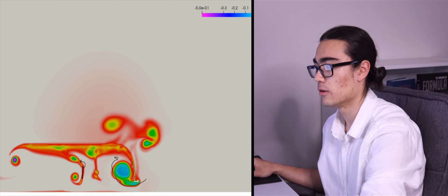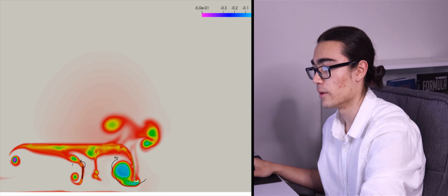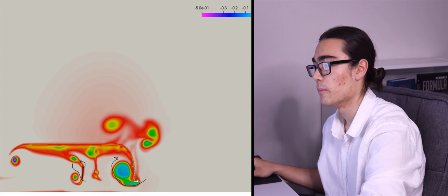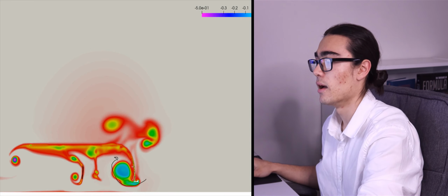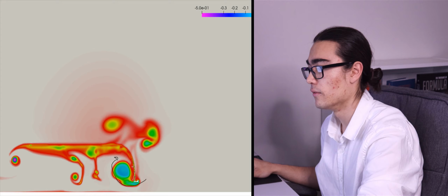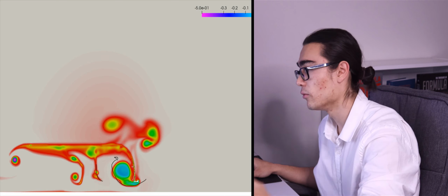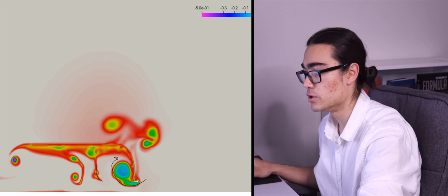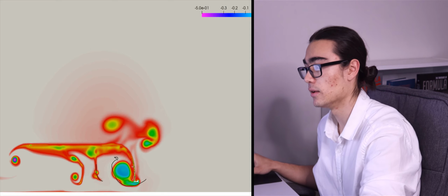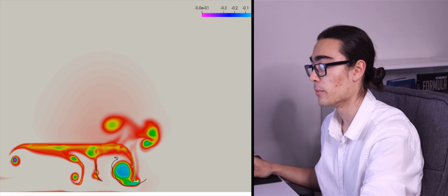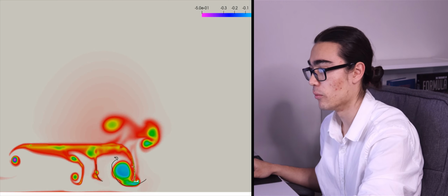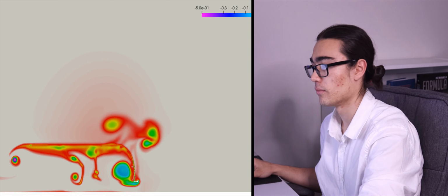But to minimize the loss of this top vortex, we could have perhaps reshaped our strake something like that. So the bottom outwashes a lot, but the top doesn't. So perhaps we wouldn't have generated such a loss off the top when it's not actually going to be doing much. The purpose again of this strake was to support this structure here, which we can compare more to the other wing. But generally the strake was designed to not make too much loss behind it, too much disruption, and that's why it was curved the way it was, and that seems to be doing its job.